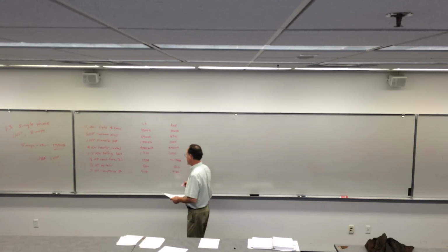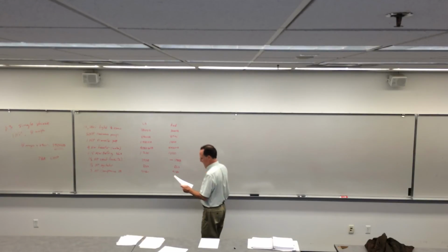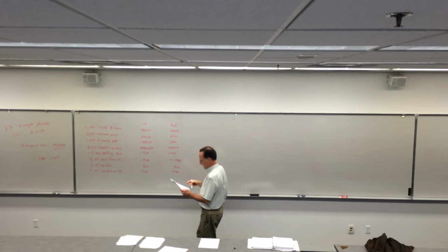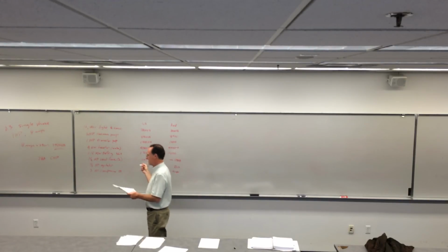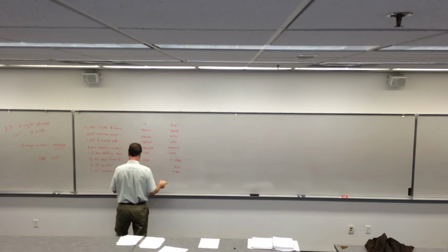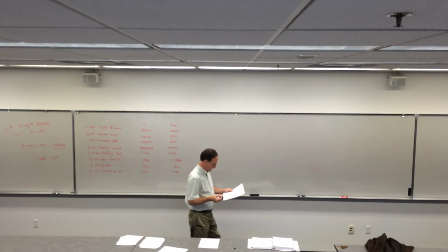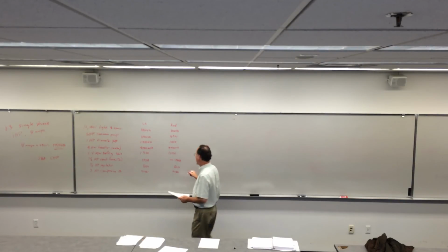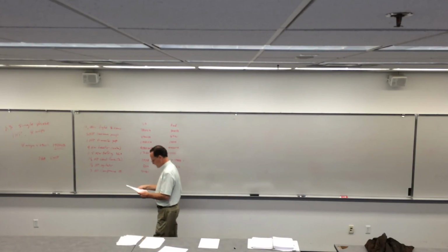You add these up, divide by 240, get your 2 different amperages, then you take 100% of the largest load, which is the load without diversity. Largest motor, which is 8,400, which is 35 amps, which is not anywhere near the 90 plus amps you get, or a 60 amp minimum on the building. So you go through that, and I ended up with around 96 amps, but I guess that would be a little low, because I should have included the vent fans.